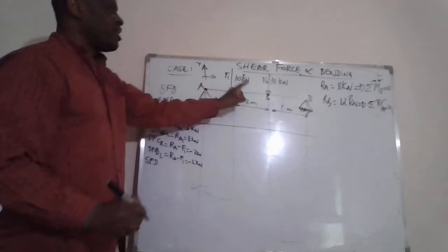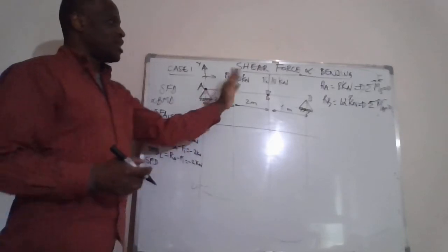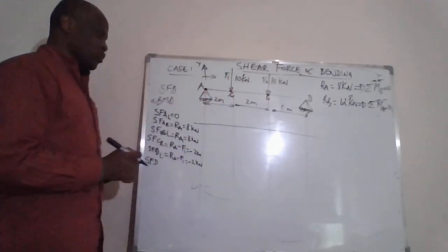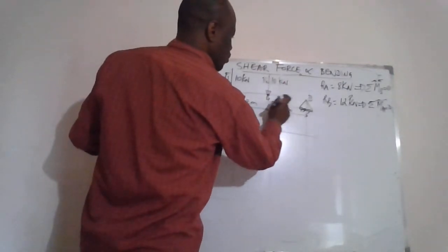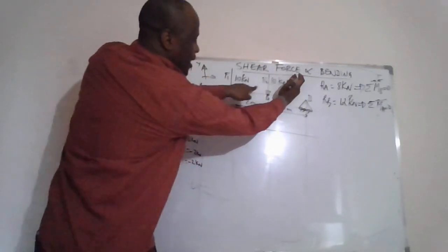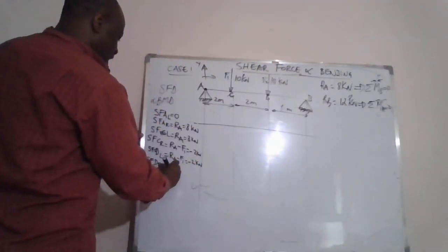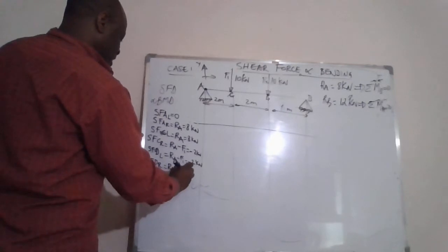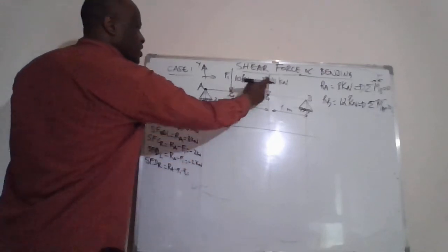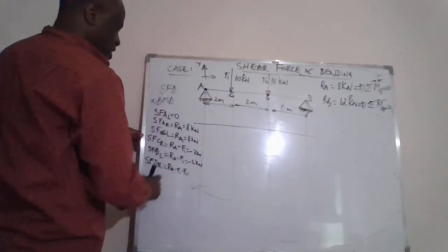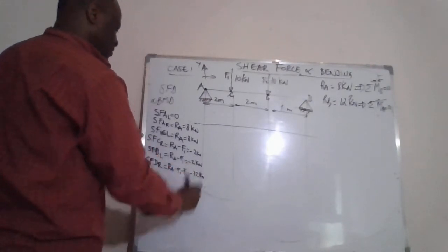We're taking left and right by definition of the shear force, and by the impact of shear force, it's always having an impact in the left and the right of the load. D right, we are here now. This is the right of D in this zone, and the remaining forces, if we do this algebraic sum, will be RA minus F1 minus F2. Minus F1 minus F2 is minus 20. 8 plus minus 20 is minus 12.